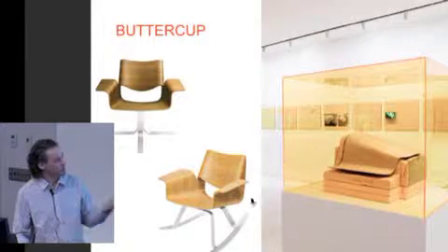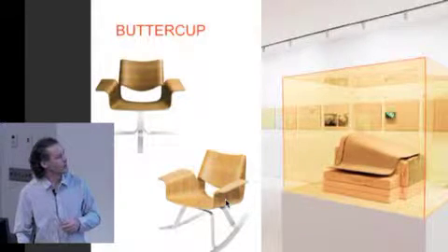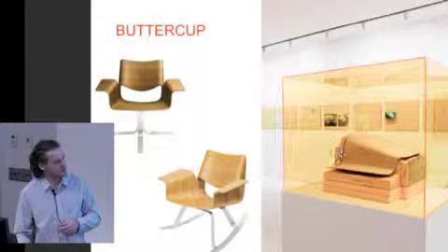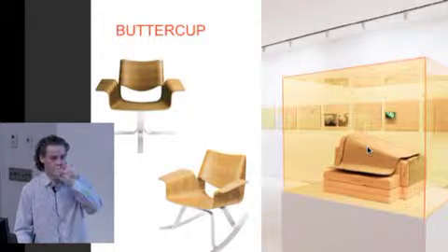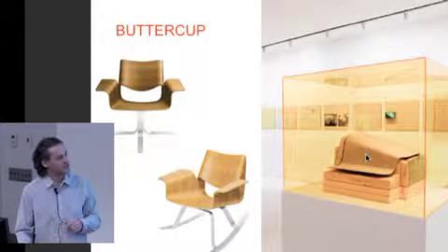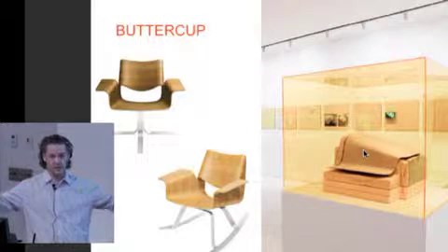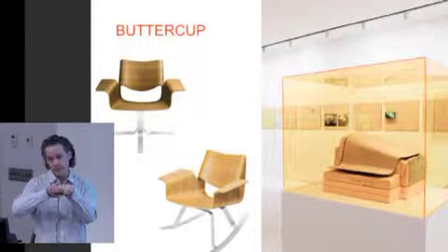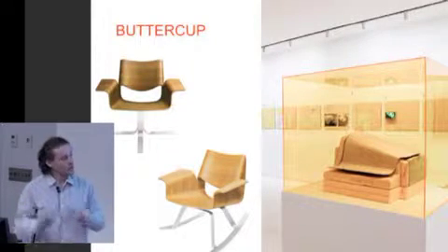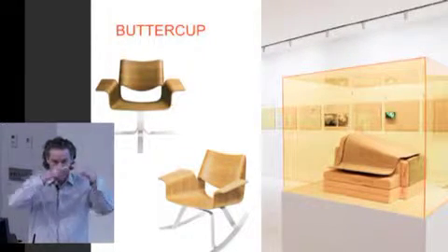And so this is called molded plywood. This is a form that the plywood layers are laid over. These thin veneers are laid over. And then that's set into basically like a giant Ziploc bag, called a vacuum bag. And then all of that air is pulled out and the bag sucks tight.